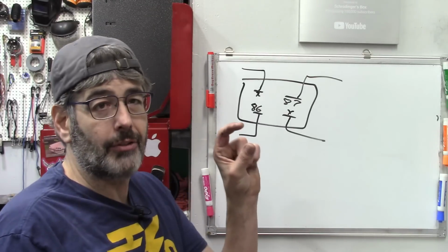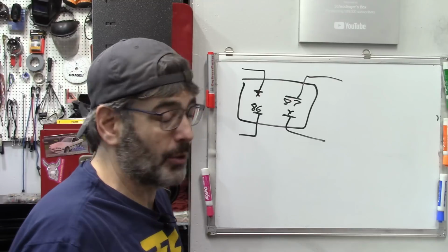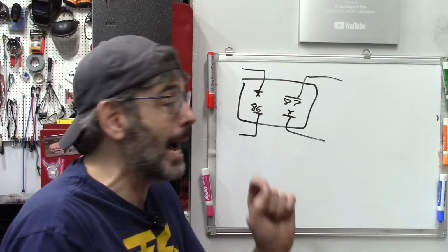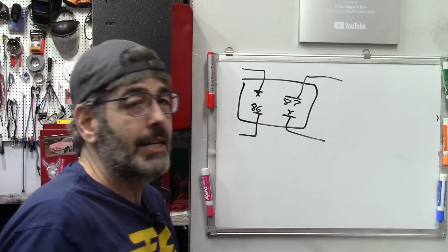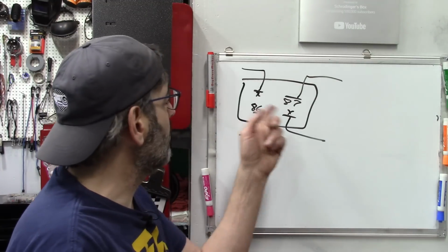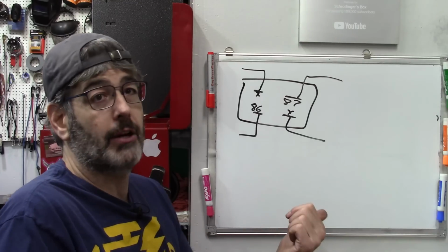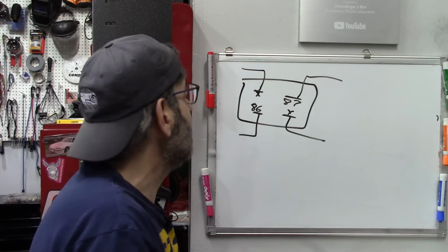Most relays will also have a little map on the back of the relay, which is going to be very helpful if you're going to be allowed to use the relay map. Not all relays have a relay map, so you either need to be able to read a diagram or, like I often do, just be able to figure it out with your DVOM or test light.